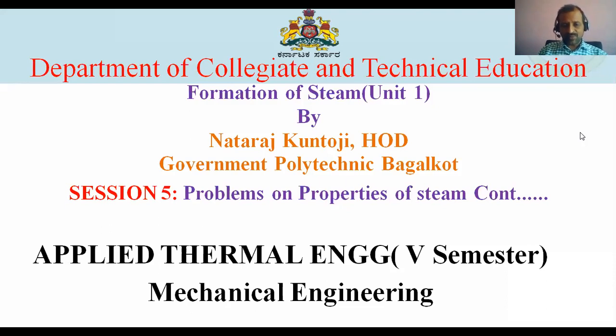In these cases, I explained there are 3 stages of steam: wet steam, dry steam, and superheated steam. These are called the conditions of the steam. In all the 3 conditions, our work is to find out enthalpy, which is nothing but the amount of heat supplied. Then next is entropy, then the volume, then internal energy, then external work done. These are all the properties we need to calculate in all conditions, whether it may be wet steam, dry steam, or superheated steam.